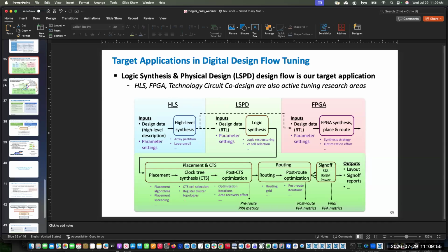I want, let's say, the AI accelerator to do this or the RISC-V to do that, then think about how you would modify the RTL and how you would adapt it. That's, I think, the beauty of open source. The other aspect is if you're interested in how you optimize it or implement it from physical design, then having a fixed RTL of reasonable complexity, maybe not too simple, not too complex, and then going through the process, seeing the metrics, and then trying to make it better.